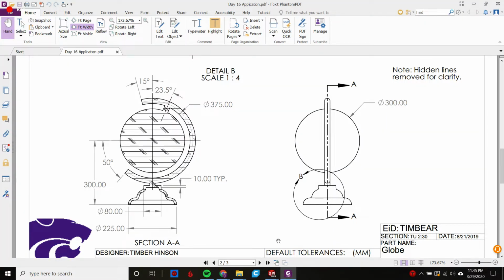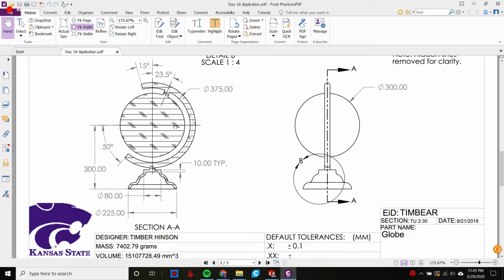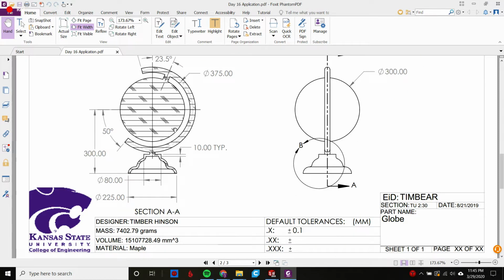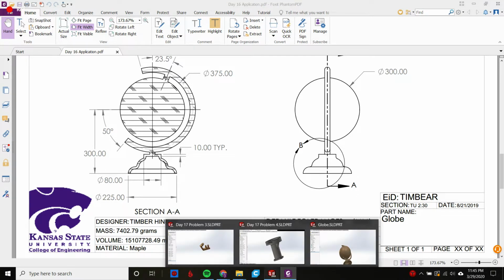But if we're taking a look here, let's see what we got. We obviously have this shell happening at the bottom, and then this sort of sweep, and then there are these connections between what's happening here. And this should be one solid body, which means there's nothing interrupting the flow of material all the way through here. It's one solid piece. But there's going to be some multi-body action in here as we're building it. So I'm just going to run through because I think this is a little tricky.